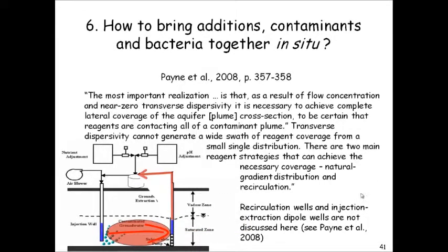The problem is that as you do this, if the contaminant is mobile, it's moving as well. So all you're doing is injecting clean water with remedial chemicals, and it's chasing the contaminated water. Contaminated water is extracted. Often that water then is brought to the surface and treated, and then recirculated with the extra addition of nutrients or oxygen or whatever. Turns out most of that treatment actually occurs above ground. It's an ex situ treatment system. So this is essentially a very sophisticated pump and treat system if the chemical is mobile.